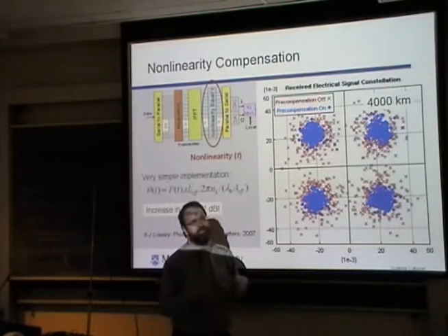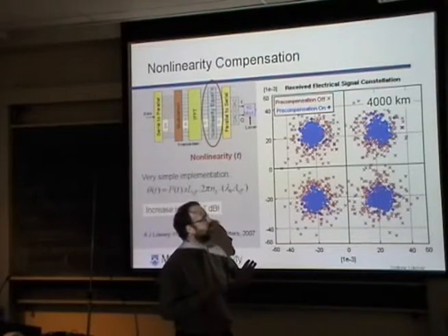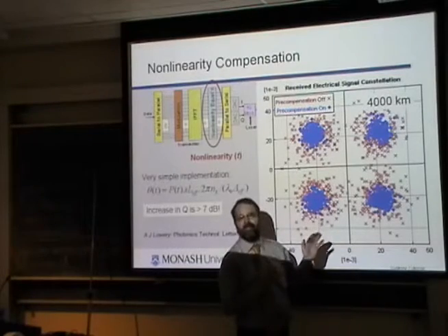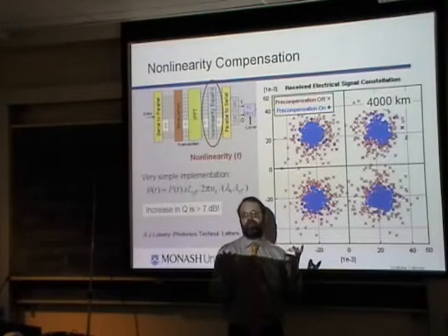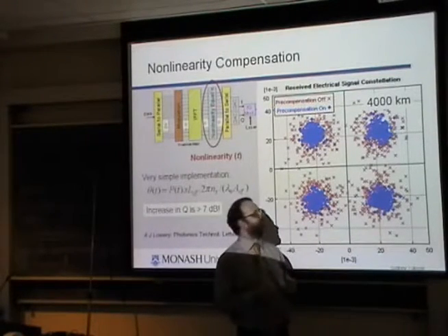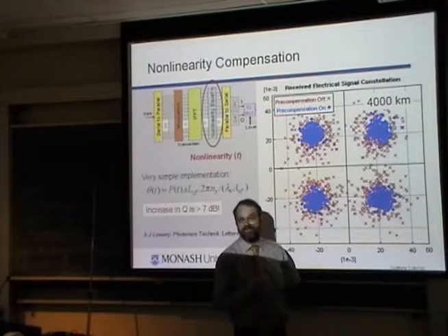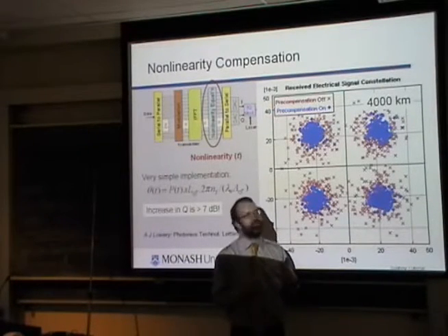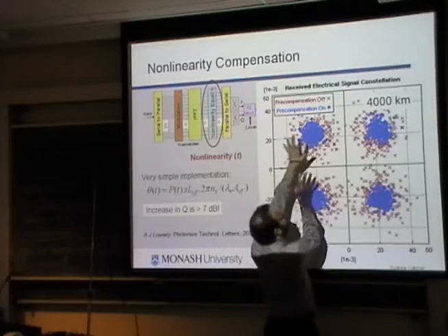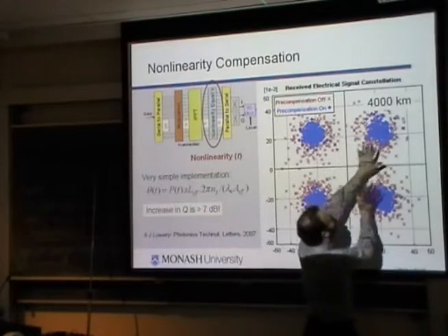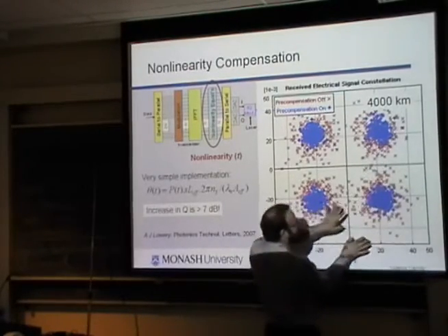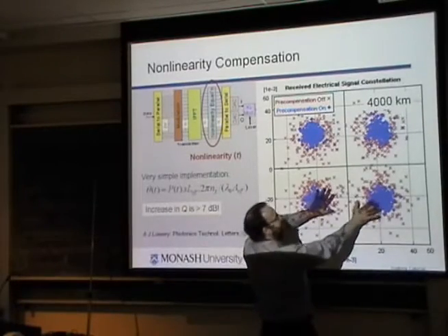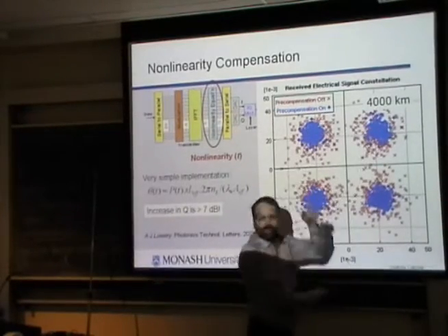It's quadrature amplitude modulation, which means you can actually send data on the sine part of the waveform or the cosine part of the waveform. And that means you can sort of double the amount of information. So rather than just sending a real signal that's either negative or positive, you can send a signal which is minus 90 degrees and plus 90 degrees in phase.